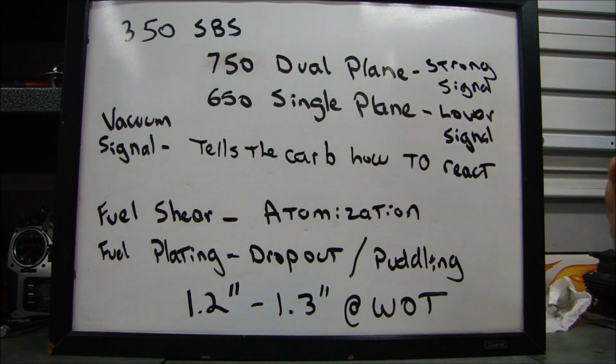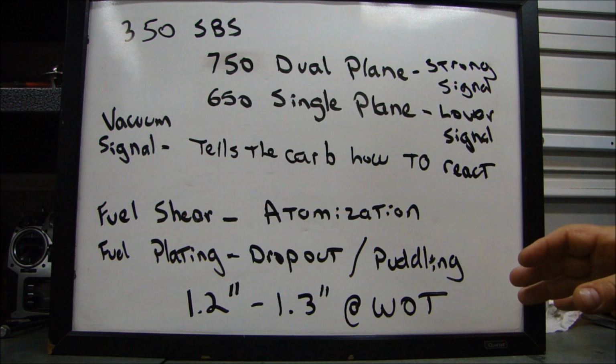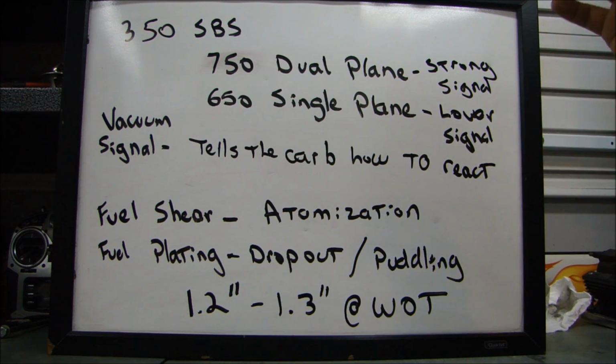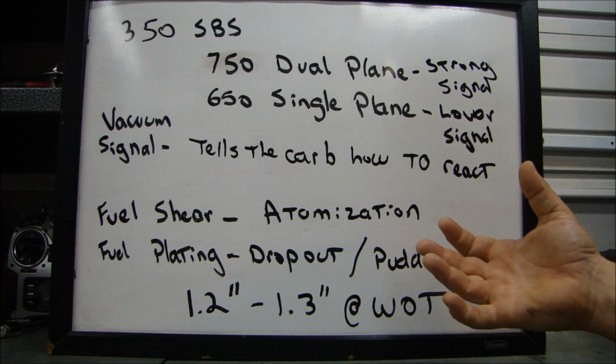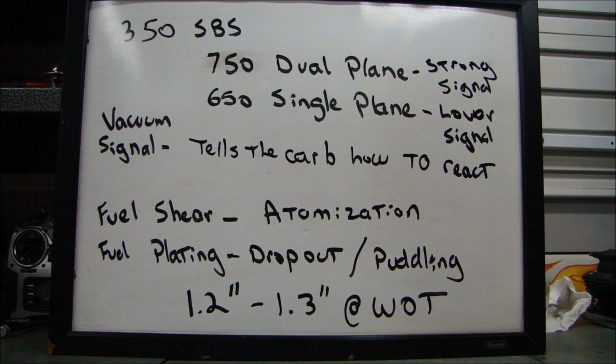But what I'm going to do really quick is show you the difference in carburetors, just the basic types of carburetors, the configurations, and some rules of thumb. So when you do your calculation, you come up with your number, and you decide: how do I know, should I go bigger or smaller based on my application?